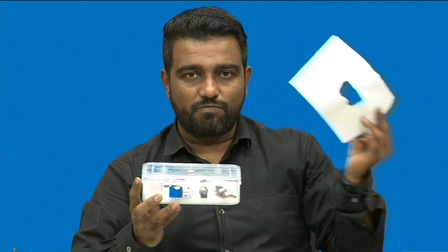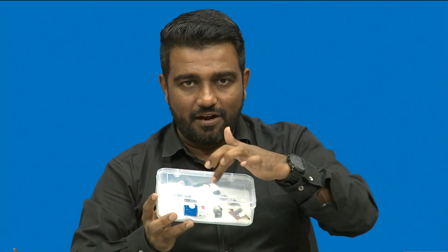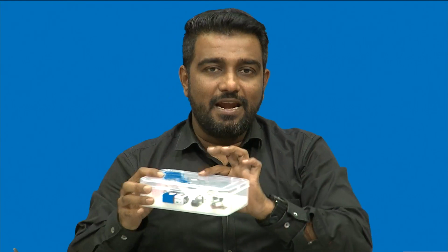So when I remove this mask, I will only have the central region with the sensing layer. Now if I heat this at a particular temperature, I have my sensing layer ready. So screen printing is very easy to work with compared to thin film, but there are disadvantages: in thin film you can have an extremely minute sensor, while in thick film it is kind of difficult.